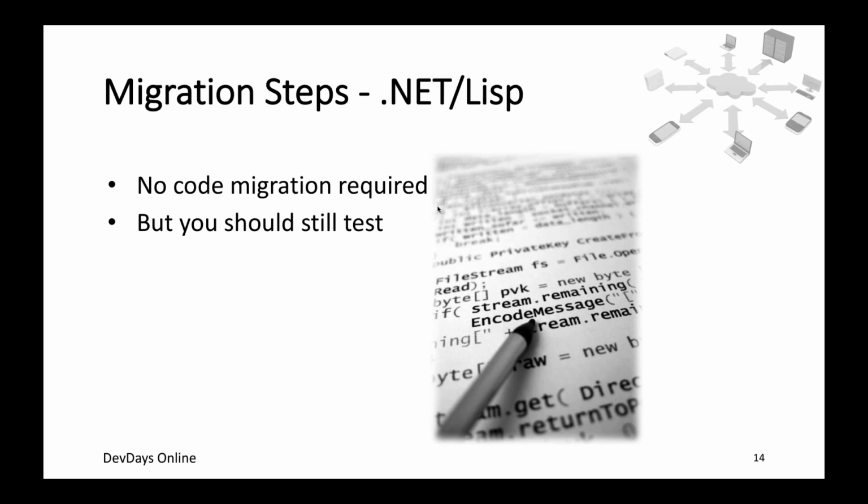And of course, just reiterating, with .NET and Lisp, if you have an app that you're publishing in the App Store and you're using, for example, the Autoloader package, you need to update that major version number from R22 to R23, so that the Autoloader will load your code in the new version of AutoCAD.